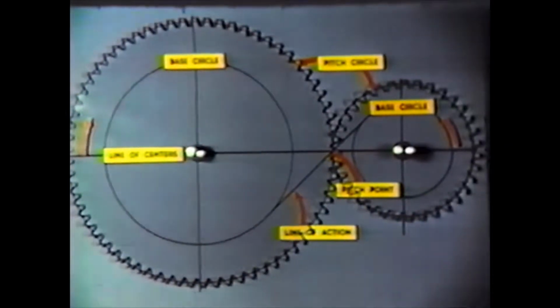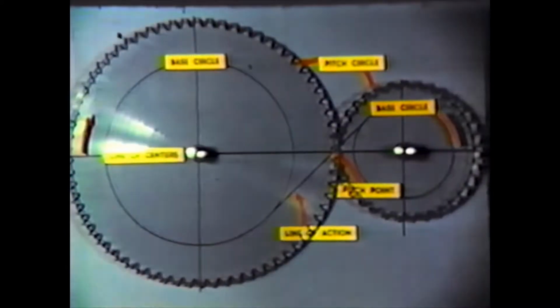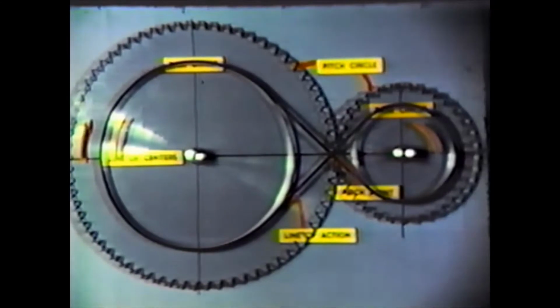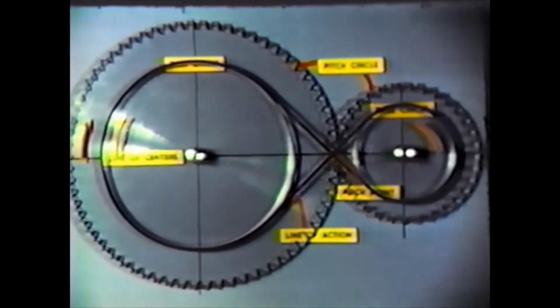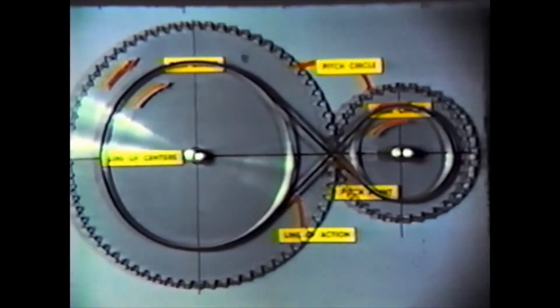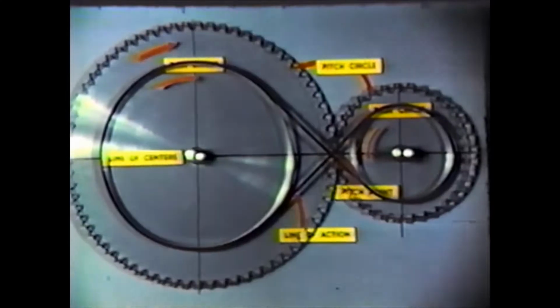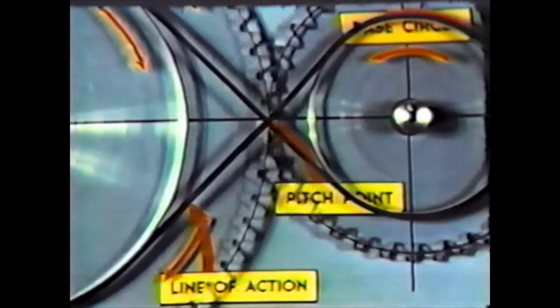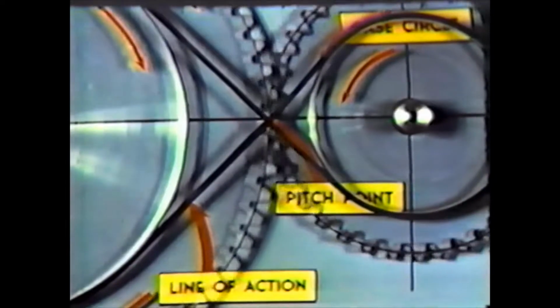These gears fit the same center distance as the original friction discs and pulleys. By superimposing the original friction discs, it will be noticed that they are the pitch circles of these gears. Likewise, the pulleys are the base circles, and the crossed belt represents the line of action. Where this belt crosses the line of centers is the pitch point, which is also the tangent point of the friction discs. As soon as a load is applied, it will be noted that only the gears are transmitting uniform angular motion. The friction discs and crossed belts are both slipping.